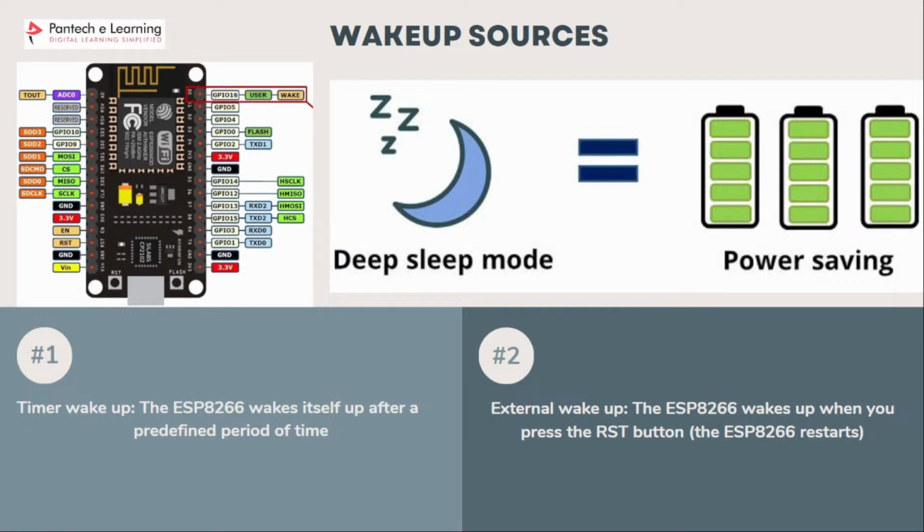The reset pin of the ESP8266 is always high while the ESP8266 is running. However, when the reset pin receives a low signal, it restarts the microcontroller. If you set a deep sleep timer with the ESP8266, once the timer ends, GPIO 16 sends a low signal. That means that GPIO 16, when connected to the reset pin, can wake up the ESP8266 after a set period of time.